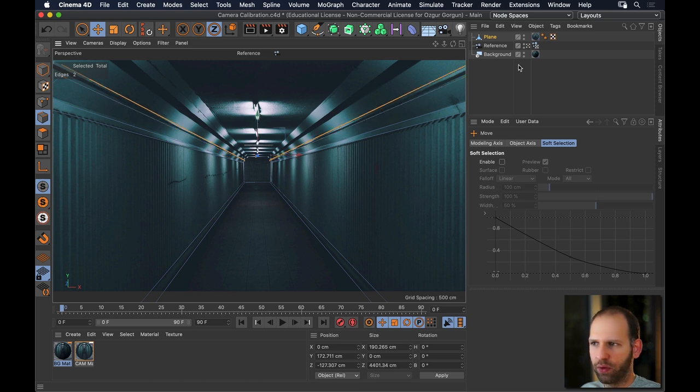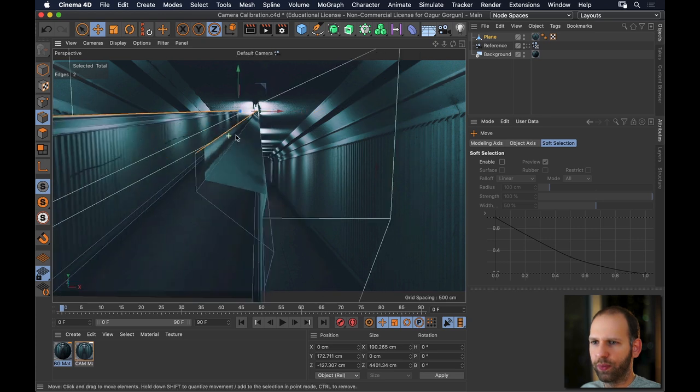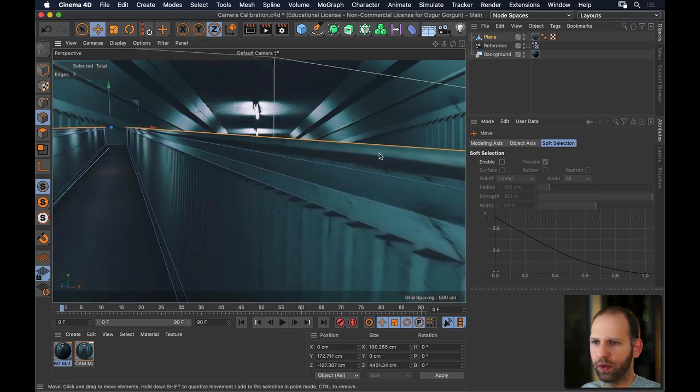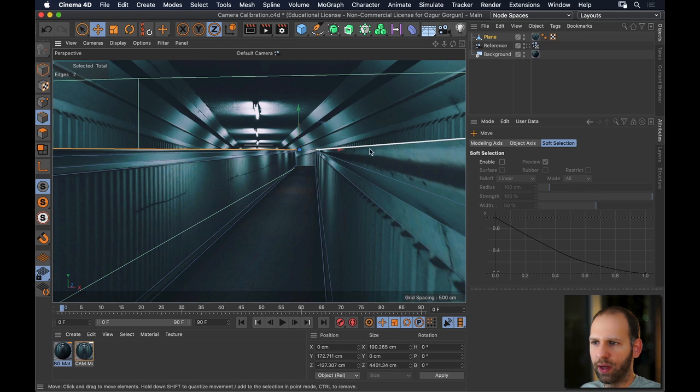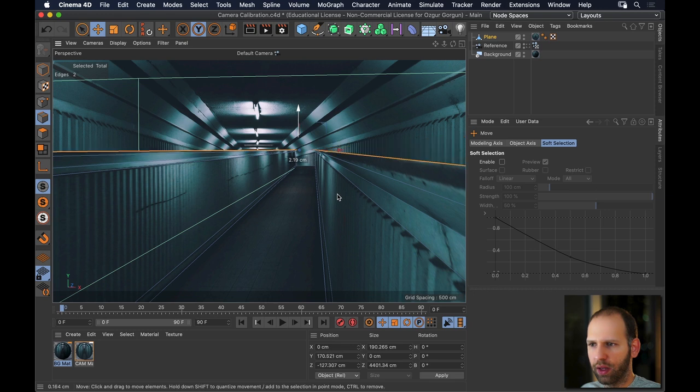That's gone too far now, so let me just go in. Here. I now want this to go down a little bit until I get to this line here, this black line. I'll now come out of this Z and turn on Y only, so I can click anywhere and just drag. And it just moves the Y like that. I can also scale this inwards.